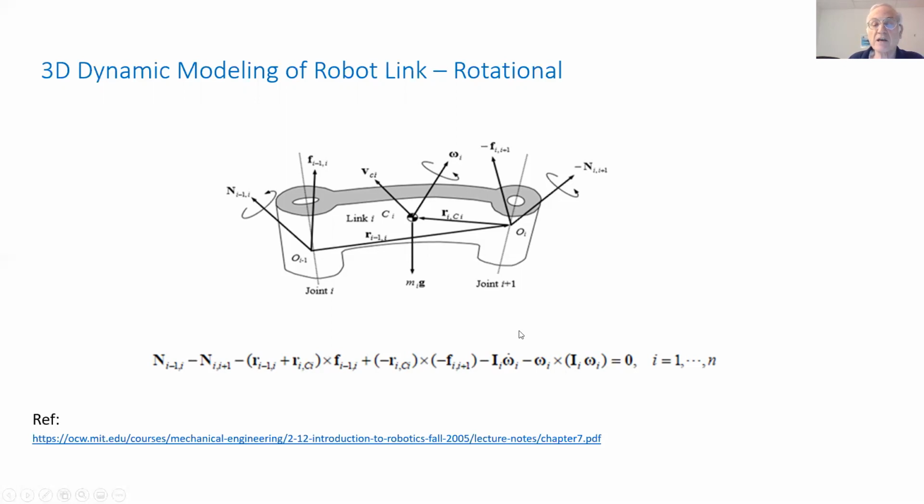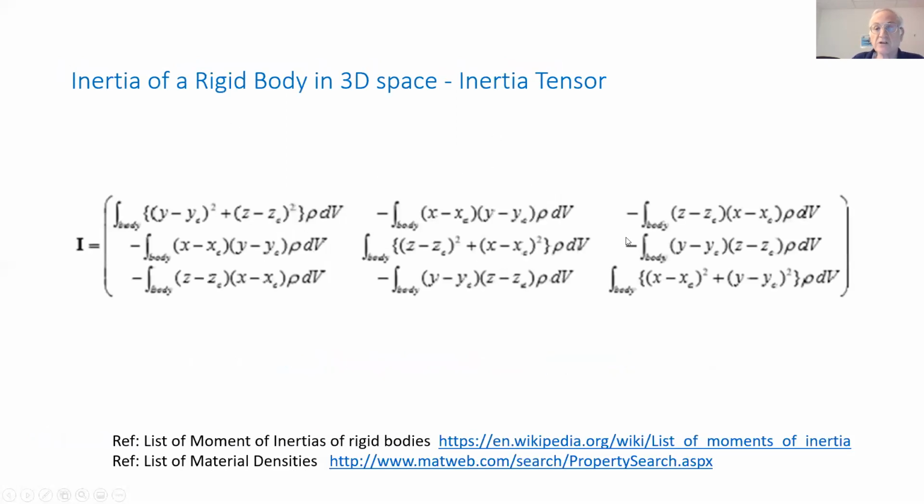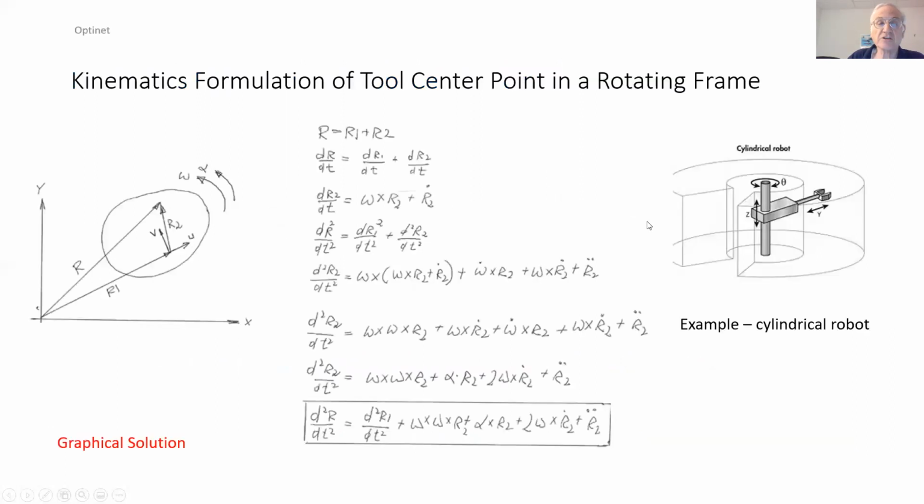And then we have the inertial torque, which is I times alpha, where omega dot is alpha, the angular acceleration of this link in 3 dimensions. And then we have on top of it the gyroscopic effect, which is the cross product of the moment of inertia times the angular velocity of this link, crossed with the angular velocity. And the moment of inertia is a complex form in 3 dimensions. This is the principal axis, and these are the cross axis inertias.